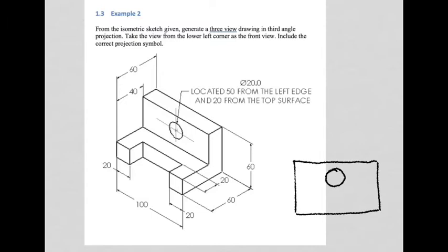You would look right through the object, and you would see a hard line over here, and you would see a hard line over there and over there, which would be depicting those edges. That edge and that edge would be visible to you. You would see nothing extra in the background here, because that hard line would be directly behind that hard line, and that would be pretty much all you would see if you were viewing the object from down here.